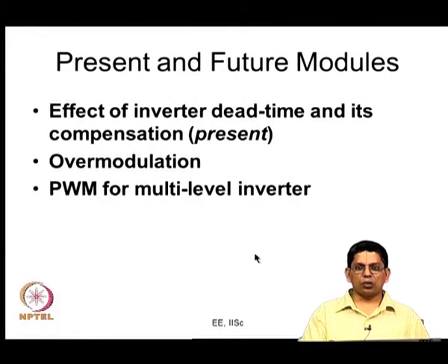Many times you can ignore the non-idealities, but sometimes you cannot. For example, when the devices are switching in a complementary fashion, there is a finite amount of time it takes to turn on and turn off. For many analyses you can say it is an instantaneous turn on and instantaneous turn off, but when you practically switch an inverter, you cannot ignore that.